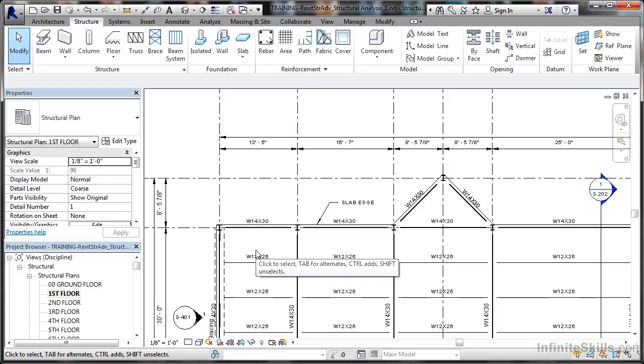The first step in preparing the analytical model is to review the structural settings in Revit Structure itself. The Structural Settings dialog box has 5 main tabs containing information for the following: symbolic representation settings, load cases, load combinations, analytical model settings, and also boundary condition settings.